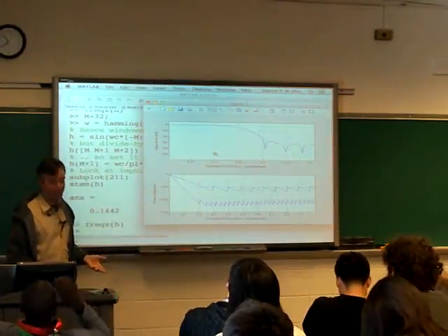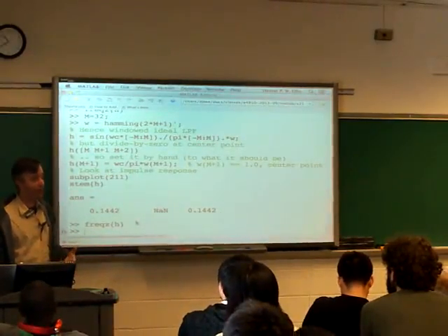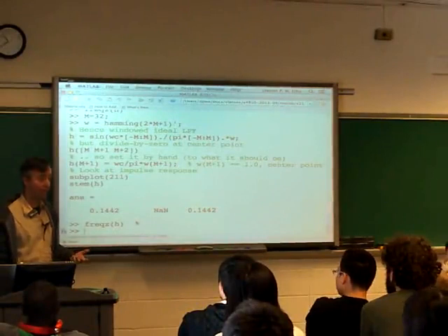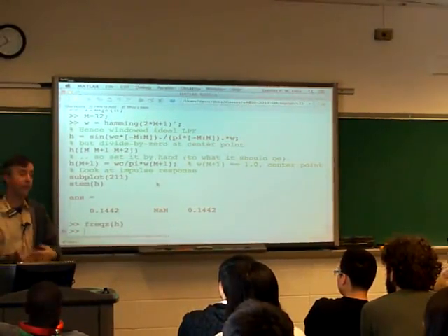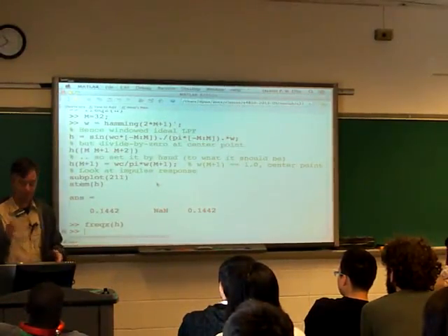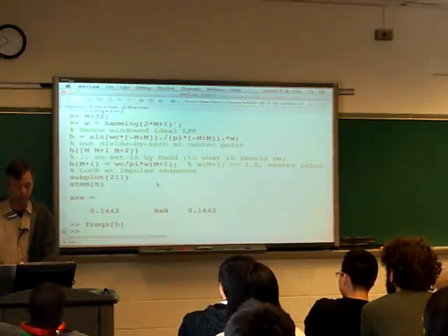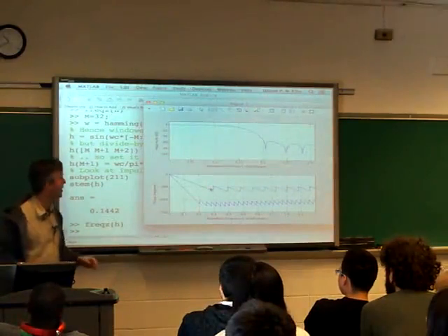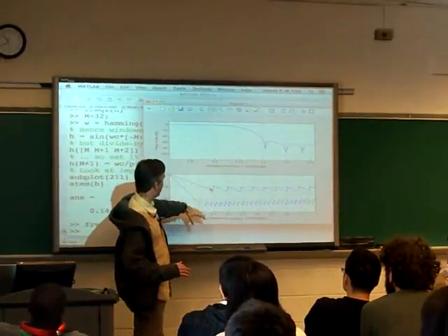But now we've got a 65th order filter, right? That's quite a lot of coefficients. That's quite a lot of calculations compared to when we tried to make a low-pass filter using like a 6th order elliptical, which was extremely sharp, extremely tight. So this is really showing you the difference between the IIR filters and the FIR filters. But on the plus side, this phase response is basically linear.